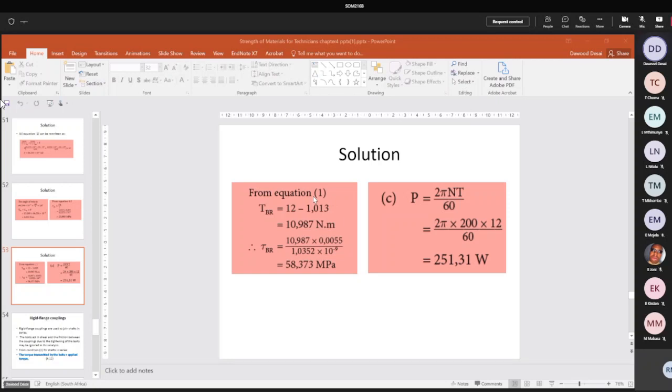Remember the golden rules for torsion. We do not work in degrees, work in radians. Write down the general torsion formula first always. Then depending on what type of problem it is, series or parallel, write down the two governing equations underneath that. Sometimes it's just one shaft. It's not series or parallel. Then you only have that torsion formula, the general one that you write down. Look carefully, convert the degrees to radians and solve. It's just mathematics, guys. Just choosing the correct formula and solving. That's what yesterday's section was and today's section was. Very, very easy. Comes with practice.